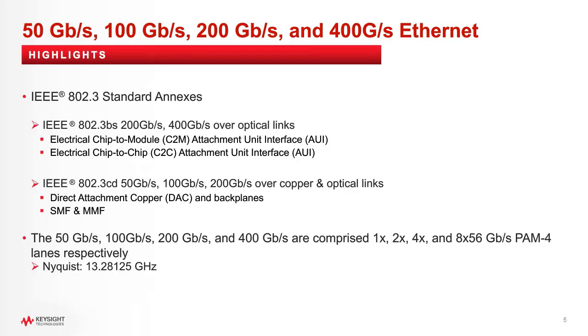These standards are comprised of 1x, 2x, 4x, and 8x 56 gig PAM4 lanes respectively, with a Nyquist frequency at 13.28125 gigahertz.